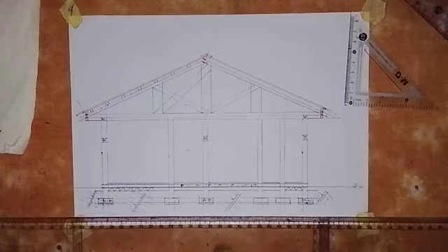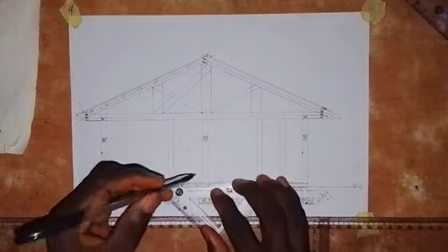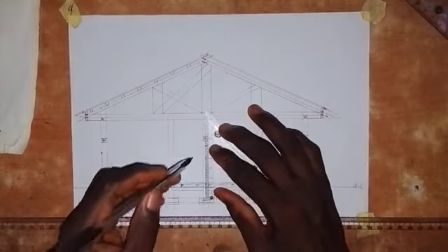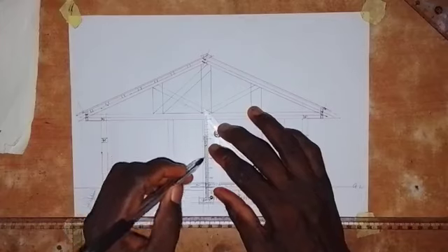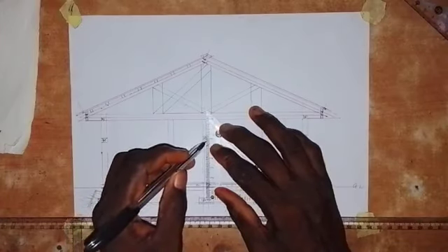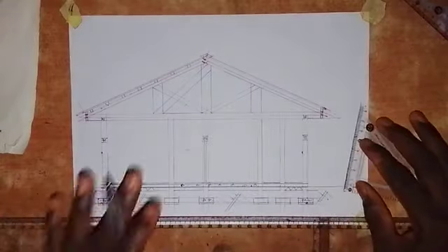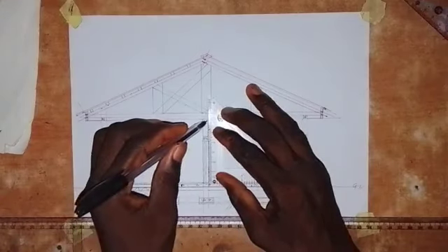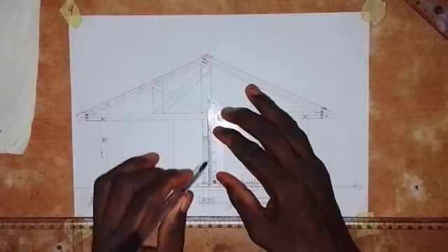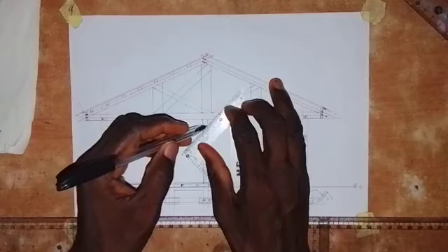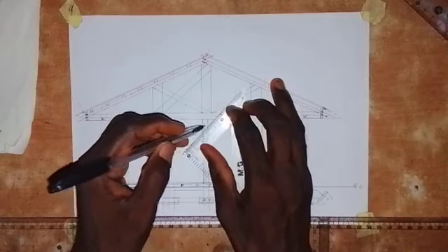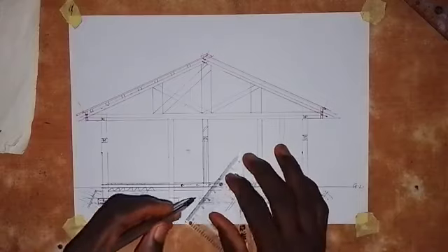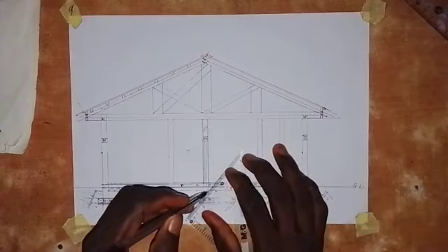All right, so then for this door that we have here, we are just going to draw 2 vertical lines within this space. So just set the ruler like this, and then draw this vertical line, and then you draw this. Okay, so the door has been fixed there. So what I'm going to do now is make this a thick line down like this. Okay, then to show that this is a wall, just draw 2 lines like this within this space. All right, so then let us also do it down here. Let's draw 2 lines like this.